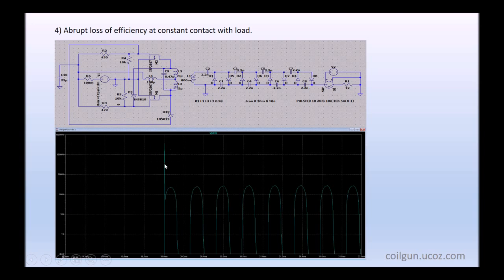This is the input pulse, and then we have a series of pulses from the output winding of our intermediate transformer, because it is directly connected to the load through such a ladder of capacitors. So our load sees only pulses, frequency pulses of our converter.